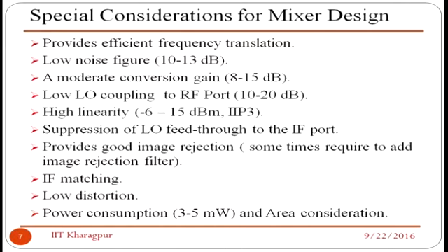Because there is a frequency translation, mind it, theoretically from the high frequency domain to the low frequency domain, I should isolate the high frequency components from passing through that mixer to the low frequency domain. If they go to the low frequency, then your purpose is not solved. And one of the basic problems is what is called LO feedthrough or LO-IF isolation and so on.